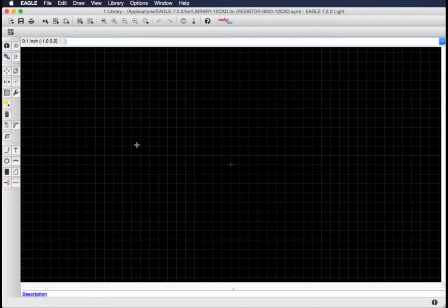Now, before I get into it, your symbol does not need to look like a resistor. It is just something to add into the schematic so it makes sense to you. Since creating a zigzag line takes a long time, whenever I create a part, since I know what it is, I just like to create a square box. It just makes sense to me. So I will create a square resistor, and it will have two pins, which are the two ends of the leads of the resistor, and we will start from there.